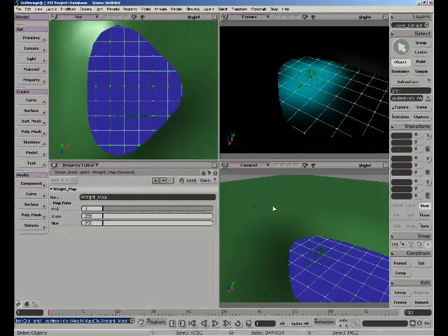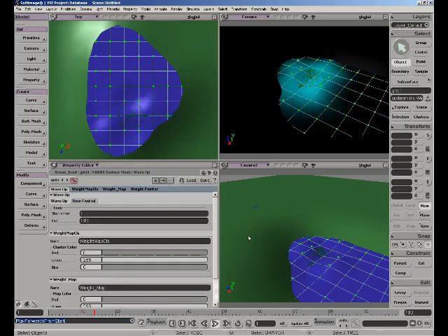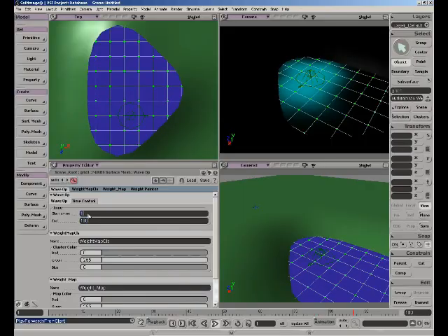We've made a number of enhancements to many of the deformers inside of XSI. For example, the wave deformer now has the ability to have time control. So I'm going to apply the wave operator to just this local area here that I've painted with my weight paint tool. And by applying the wave operator, you can see that it's now only going to affect that local area.